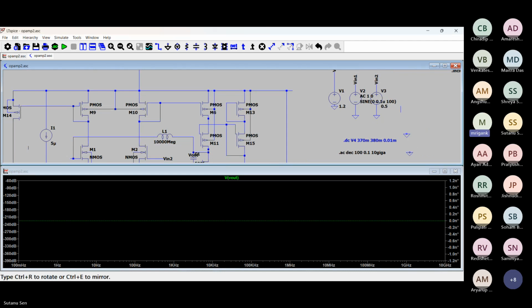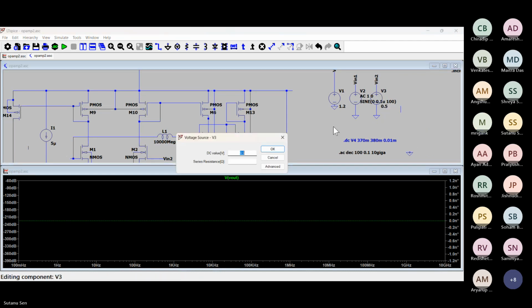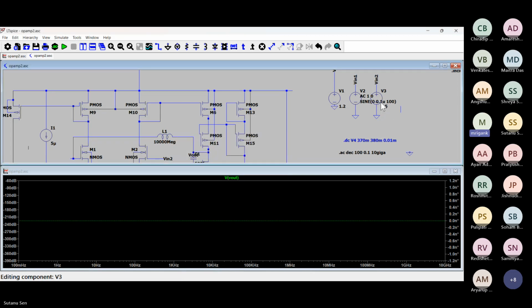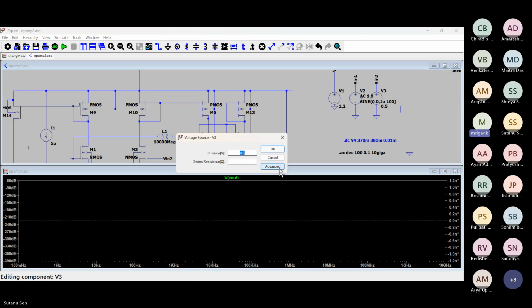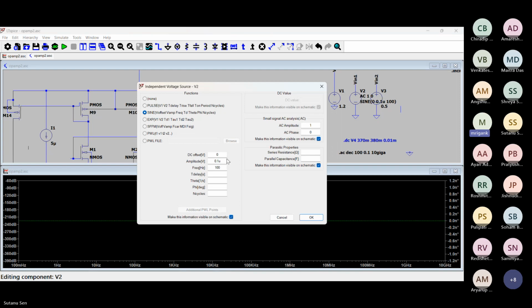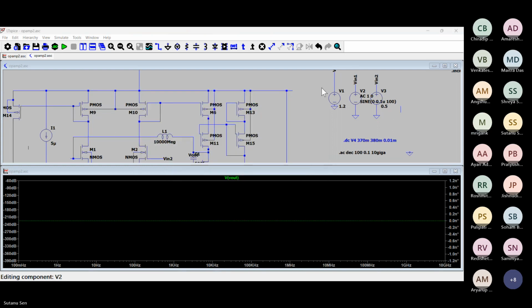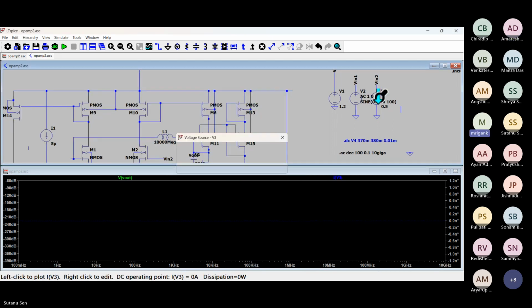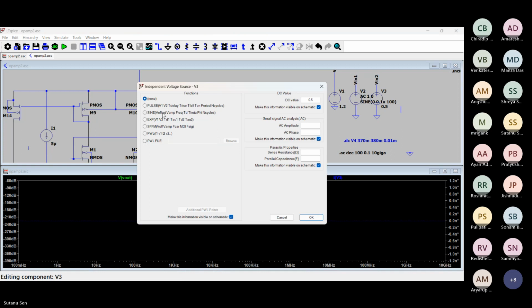What we are trying to do is put it in voltage follower configuration. As far as DC is concerned, for DC omega L is 0, so it is like a voltage follower for the DC. Whatever the output voltage is, it should automatically develop equal to the negative terminal voltage. Or you can do the DC analysis also and try to find out what DC voltage is coming.